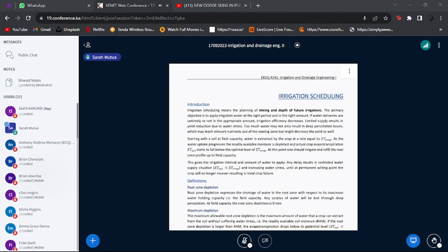Number 2, we also do not want to add so much water that the moisture goes above moisture content at field capacity. What does that mean? What is moisture content at field capacity? Just to remind ourselves, moisture content at field capacity is that moisture which is held by the soil matrix against gravity. What do we mean by that? It is that moisture that is held against gravity.